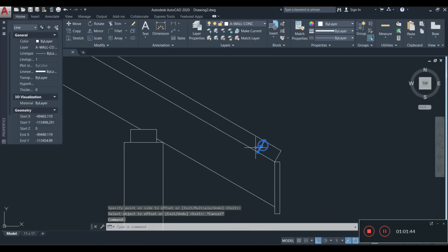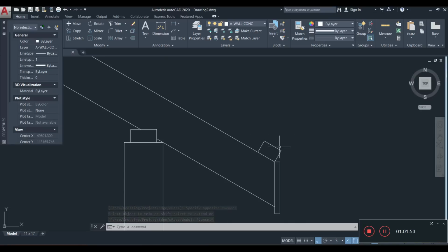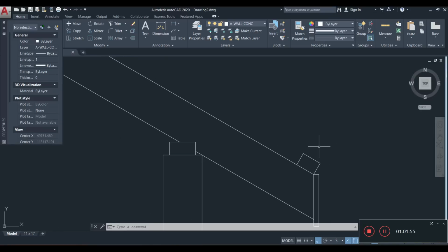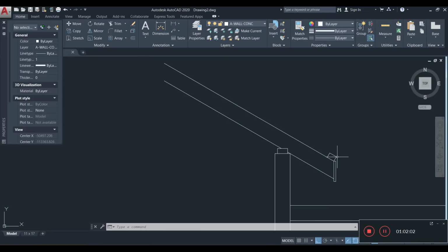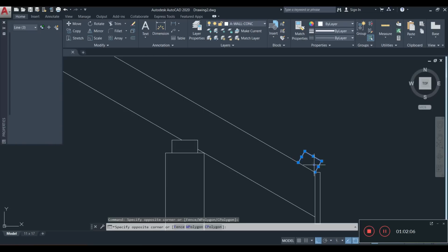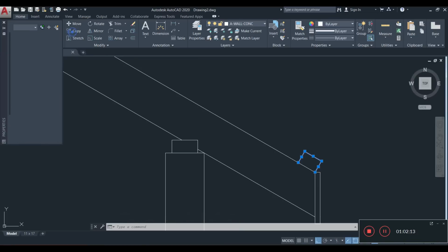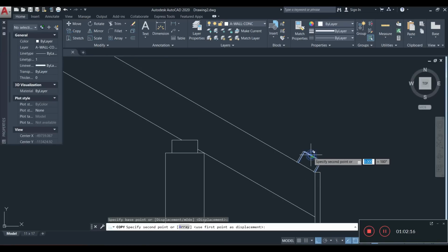Now, the spacing for these: in the Caribbean, or I'm going to say Jamaica, they will space them 600 millimeters apart on center. And again, as I said, in America and Canada and those places, they're not really going to go beyond 16 inches, which is 400 millimeters. But in the interest of time, I'm going to be copying mine on center at 200 millimeters, but bear in mind standard may vary, for those international persons watching this one here.